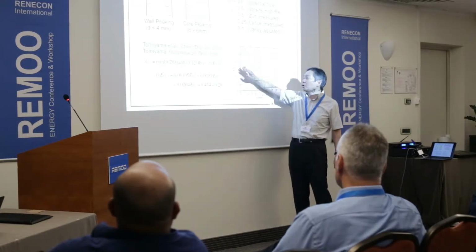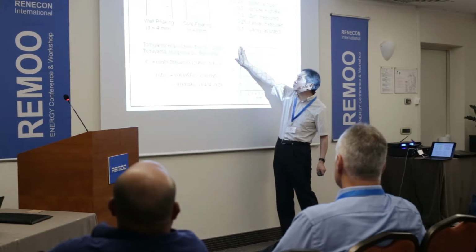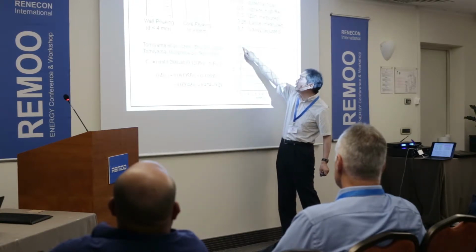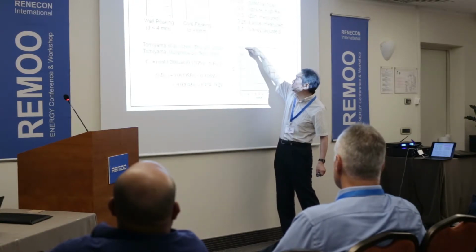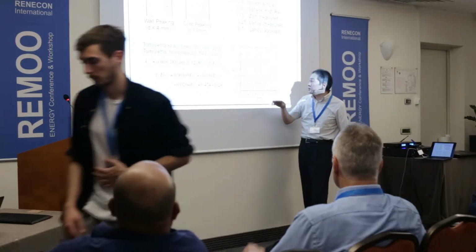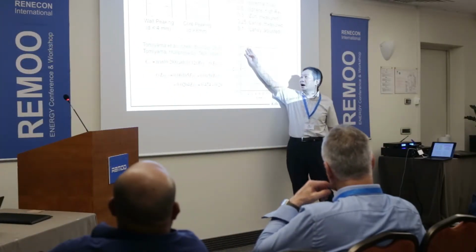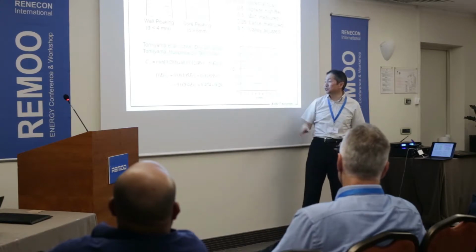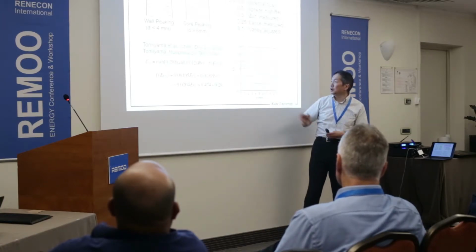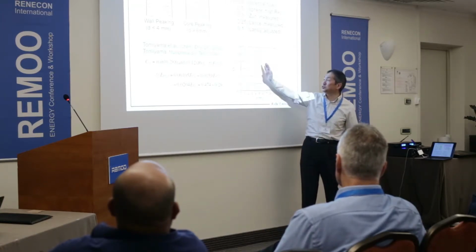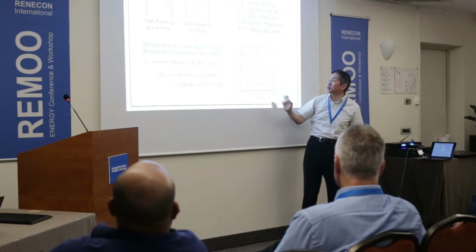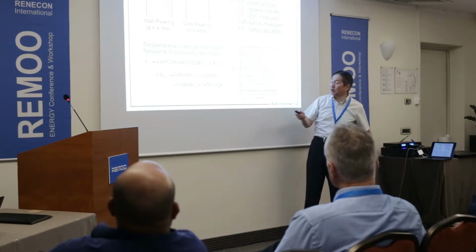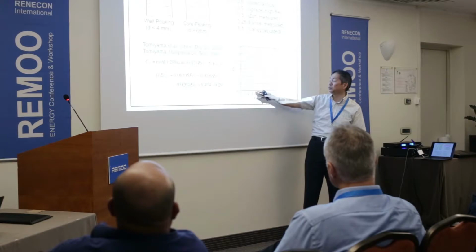And it says that, well, this point is not based on the experimental data. Actually, based on the experiment, it goes in this way. Okay? And it changes sign. When the bubble size becomes larger than 5.5 millimeter, the lift coefficient changes sign from positive to negative. So it means that the migration direction changes depending on the bubble diameter.